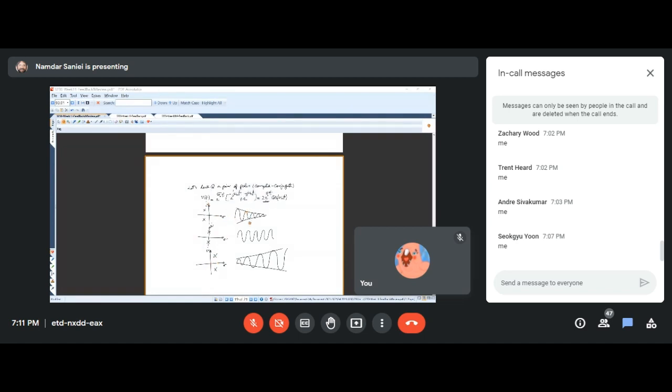One is that the circuit can oscillate and die out. The other one is that the circuit can oscillate and grow to infinity, which is very bad. And another one is that if we could keep the poles on the imaginary axis, then it would actually be equivalent to a sinusoidal wave. So the oscillations would stay as they are. They won't die, they won't grow.